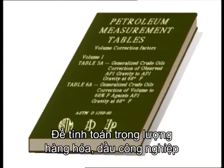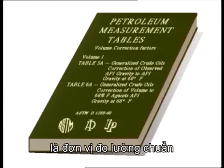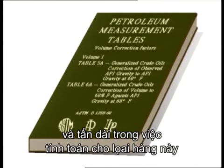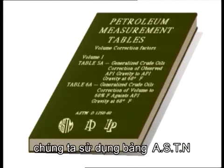To calculate weight of cargo, the oil industry mainly uses API gravity at 60 degrees Fahrenheit, or alternatively, density at 15 degrees centigrade as standard units of measurement. The loading orders for this cargo were given as API at 60 degrees Fahrenheit, so use this unit and long tons while working with this cargo. First, convert this gross volume to a net volume at a standard temperature of 60 degrees Fahrenheit using the ASTM tables.